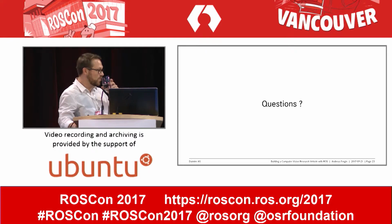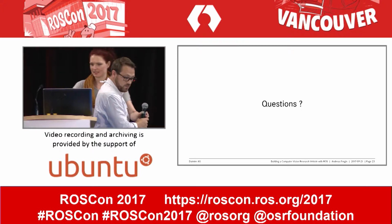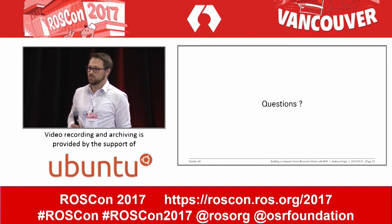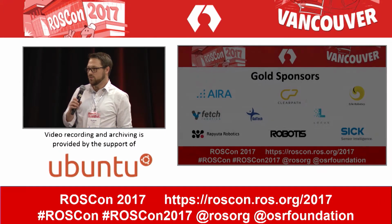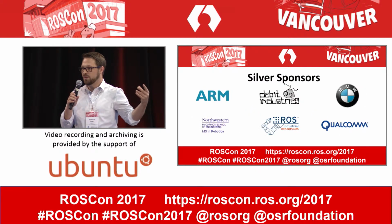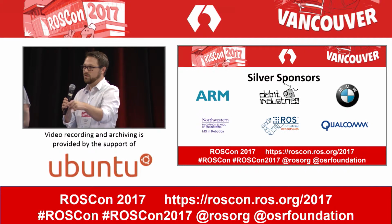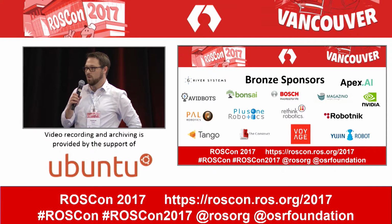There's one here. For your extrinsic calibration, your node diagram showed a node called total ST. So are you using a total station to track and develop the extrinsic calibration from that? That's right. Great idea. I simplified the slide a little bit, but we are using a total station, and we do an initial measurement of the car frame. So we measure the 4 wheels, and then we get the car frame, and then in the same run we calibrate all sensors.